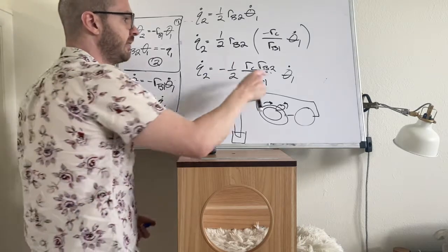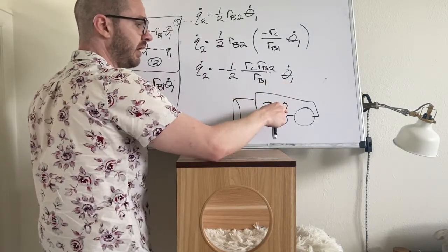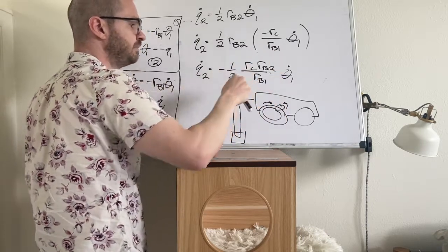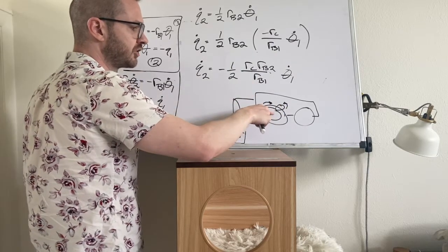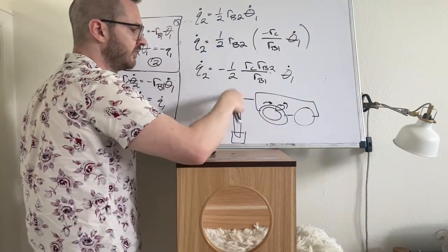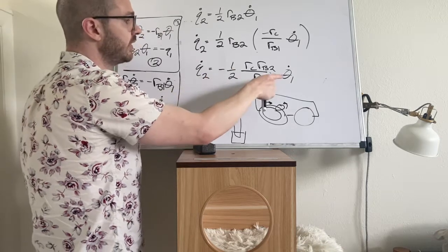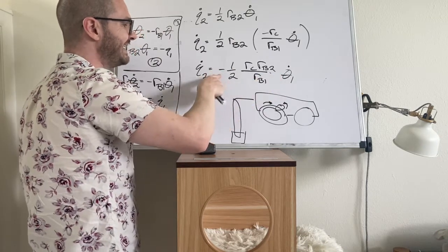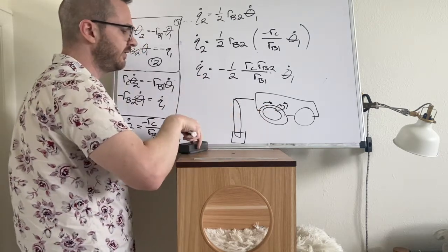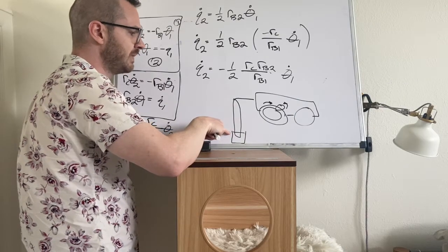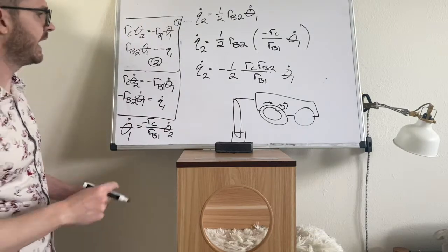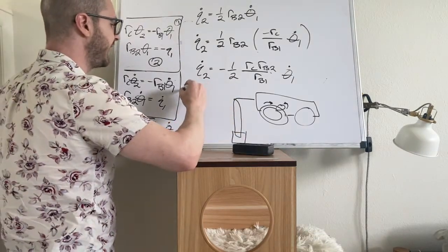So if we take a positive value, positive angular velocity on the gear, we have this kind of chained gear ratio now, resulting from the electric motor being on the inner radius and then the outer radius being in contact with the road. We have the thing because of the looping, and then we put a negative on it. So if theta 1 dot is positive, we get negative Q2 dot. And remember a minute ago, because of how we defined it, a negative Q2 dot means that this thing is actually moving up.